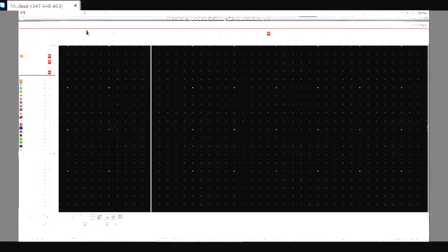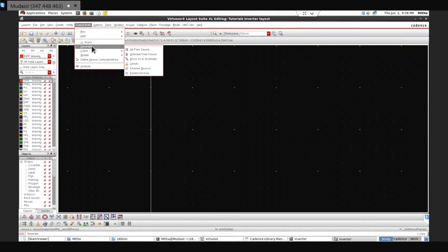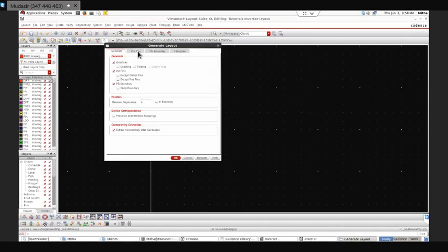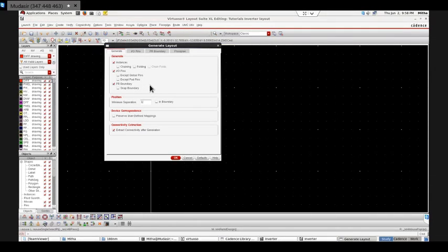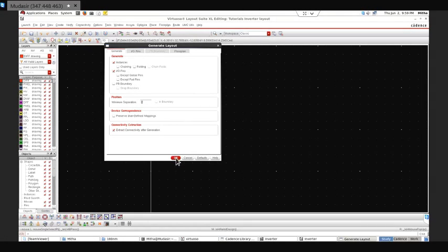Another way is to go here, Connectivity, Generate, All from Source. What it will do is generate all the transistors that are present in our source file, that is the schematic file. It will generate their layout view in this one, like here, instance. I will also select generator input outputs, PR boundary I'll also select. Let's keep this, it's not required for now. This minimum separation you can put different when we are selecting PR boundary. Let's keep it like that for some time. So I am choosing OK, then I press OK.